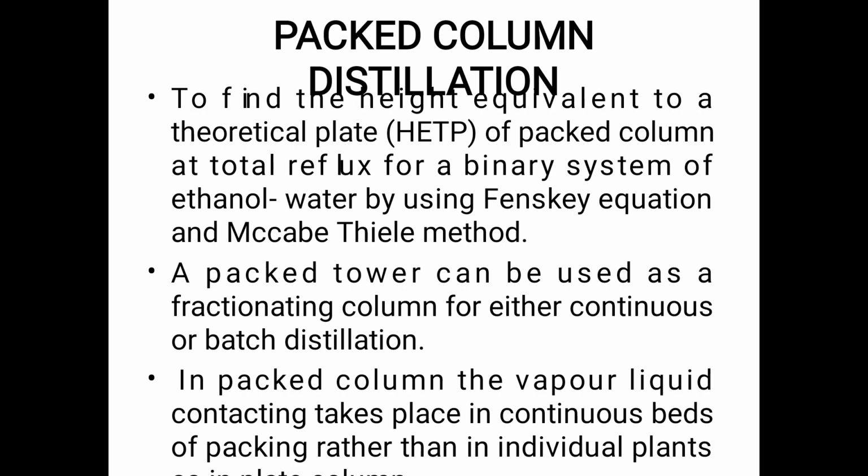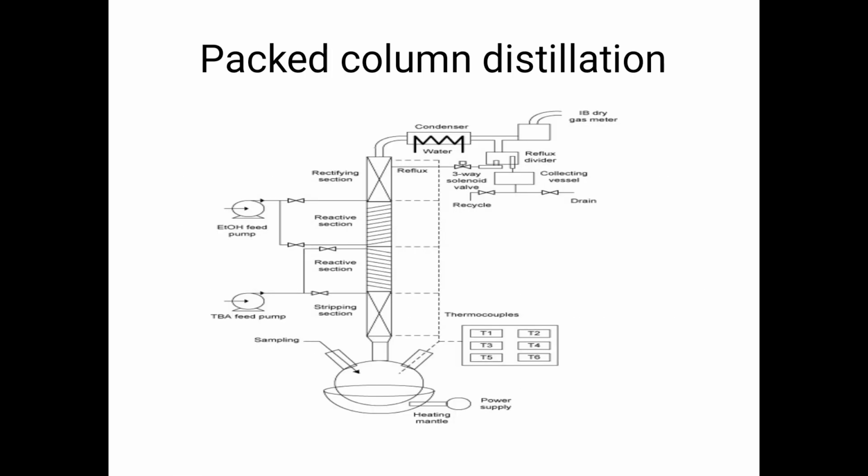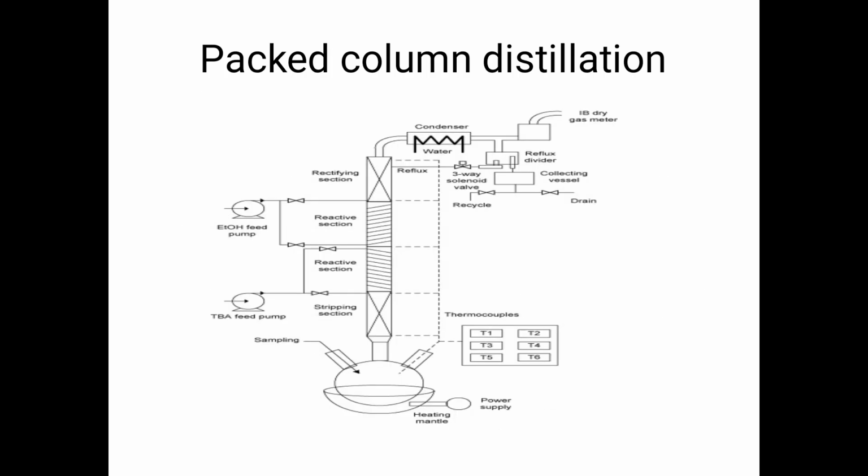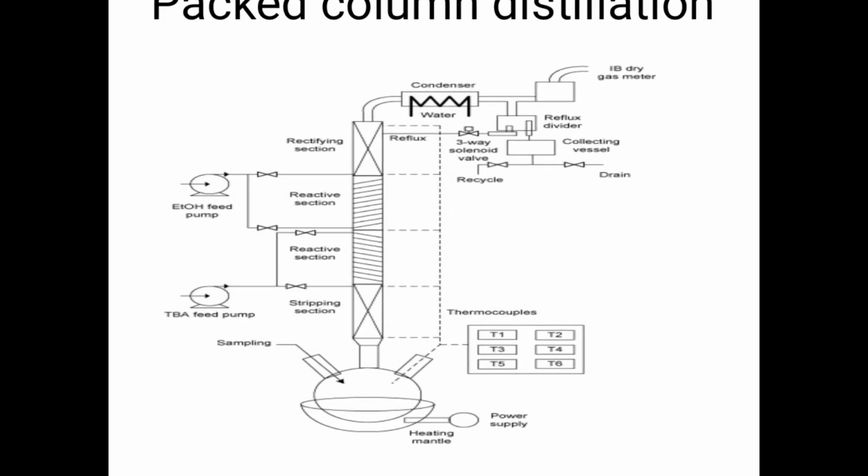A packed tower can be used as a fractionating column for either continuous or batch operation. In a packed column, the vapor-liquid contact takes place continuously through the packing rather than on individual plates. This is the packed distillation column. In that distillation column, we fill the packing material as regular packing.